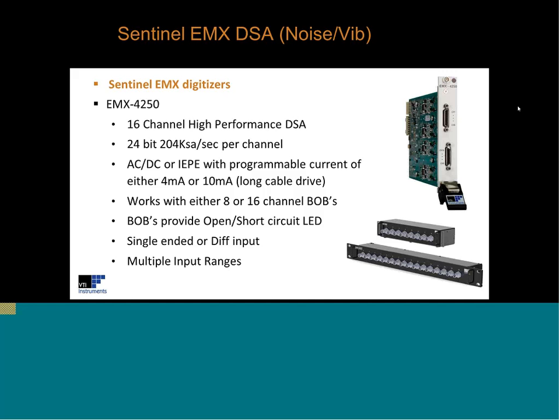Now we have a number of different breakout boxes. Here we're showing an 8 and a 16 channel. The breakout boxes do have an LED that shows open and short circuit. It actually can be programmed to also show overloads. You've got the ability to do single-ended or pseudo-differential, and you've got a number of different input ranges on this card. So it's a very capable card that gives us additional functionality and capability than we had with the VT 1432. Next slide, please, Chris.